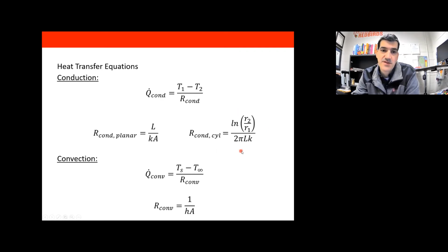All right, so we used those a week ago or so. So you've got to calculate these. Once again, you can have conduction in series or in parallel. So you can combine these in series or in parallel. But once you do, you get the thermal resistance for conduction, and you plug that into this equation, and out pops your rate of heat transfer, Q dot. All right. Then the next time we talked about convection heat transfer. Convection's a little bit more challenging than conduction.